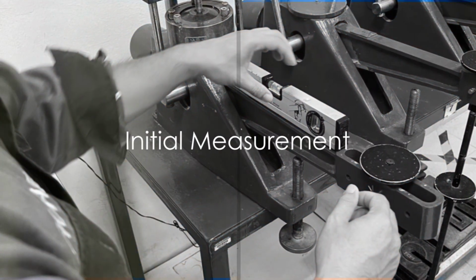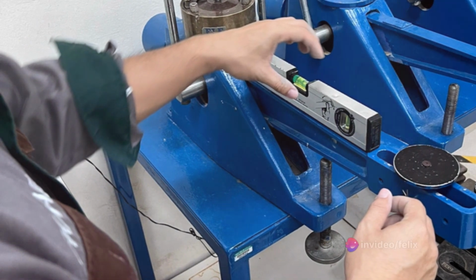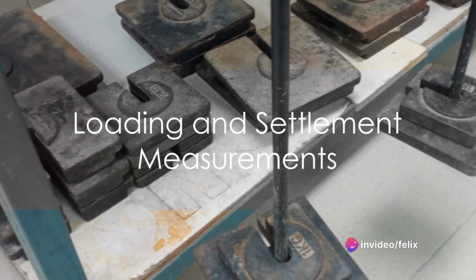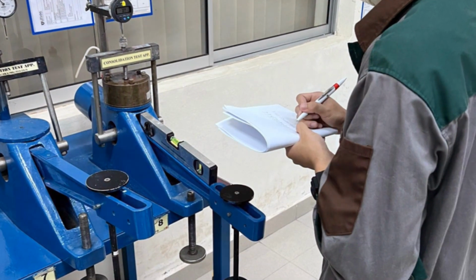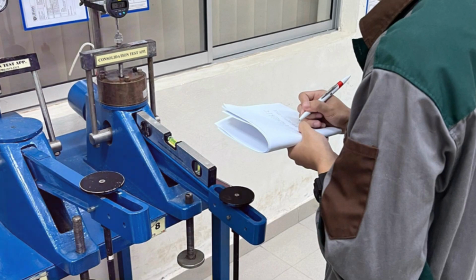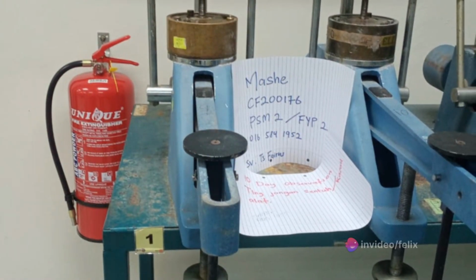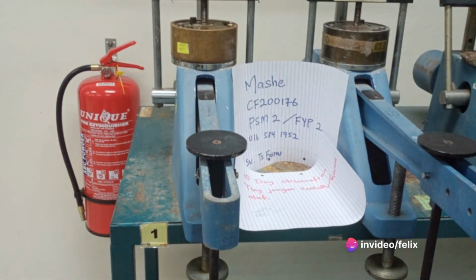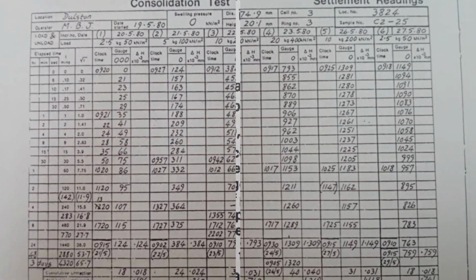Measure the initial height, h0, of the soil sample. Apply a small initial load to the soil sample to ensure proper contact and minimize air voids. Gradually apply loads to the soil sample in equal increments. Allow sufficient time for the soil to undergo consolidation at each load increment. Measure the corresponding settlements, ΔH, at regular time intervals until the settlement rate decreases significantly. Record the applied load, corresponding settlement, and time at each reading.